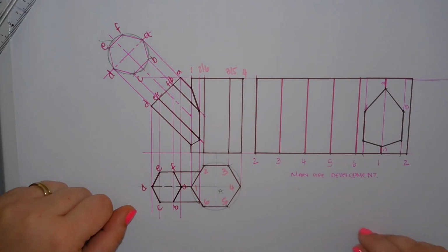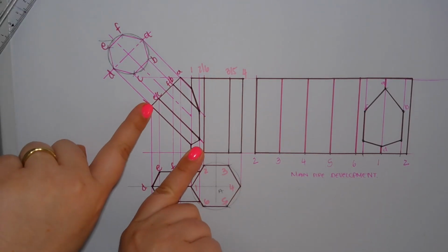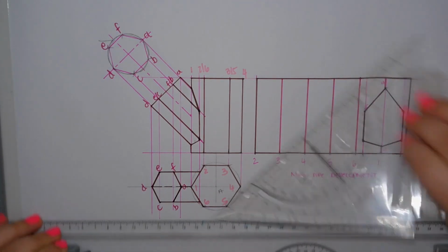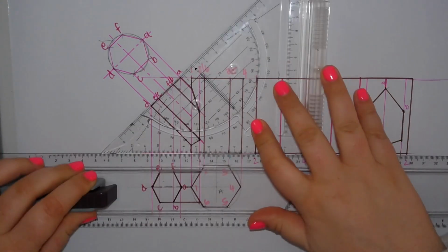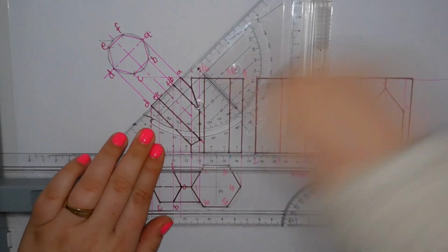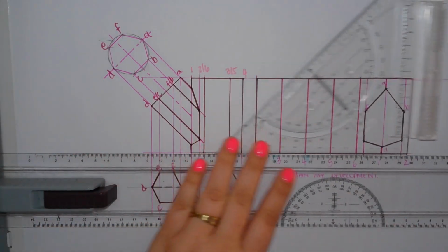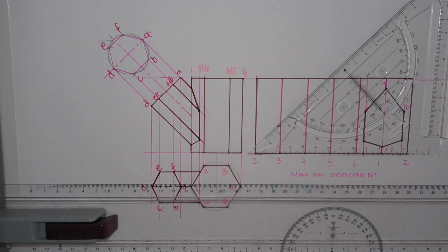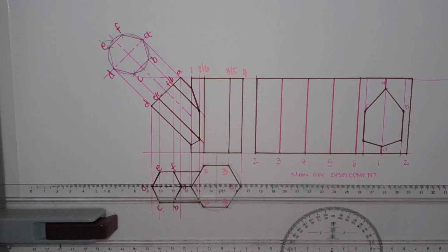What you can do is you can also project at this angle. I think it's 45. Yeah, you can project at the 45 angle, then you don't have to measure and plot as much as I'm going to do, but I'm going to be drawing flat just for future questions' sake, because what if you don't have space to project? Okay, so to start, I'm going to need the height.